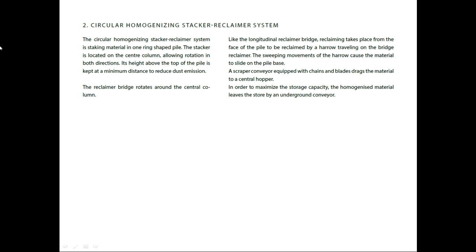The reclaimer bridge rotates around the center column. Like the longitudinal reclaimer bridge, it reclaims from the face of the pile by a harrow traveling on the bridge reclaimer. The sweeping movement of the harrow causes the material to slide down the slope.